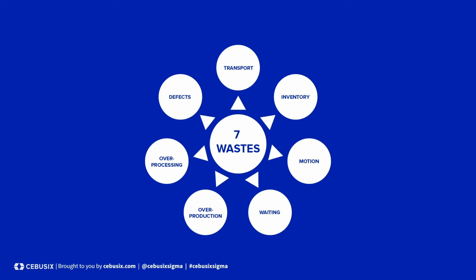Producing too much is overproduction. Anytime there is a bottleneck in the process, there is waiting. If employees are not effectively engaged, then their talents are not fully utilized. The output of one process should flow into the next rather than having to be transported. Warehousing inventory means it is sitting idle. Employee actions should have a fluid motion, and performing unnecessary processing steps to finish a product are all types of waste.